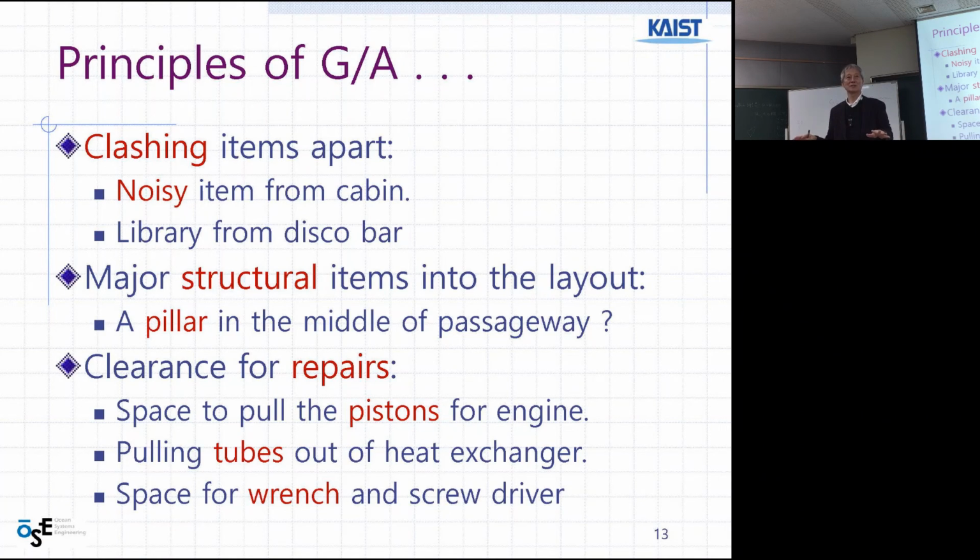Same as here, right? We don't have a pillar in the middle, because we want to see everybody at once. But for the structural designers, this is not good. They want to have a pillar here in the center. That is more stable for structural designers. Less concrete is needed if we allow a center pillar here. Otherwise, you have a bigger bending moment or loading, so that it can be spread out into the surrounding.